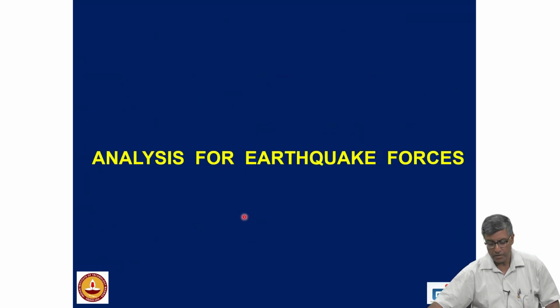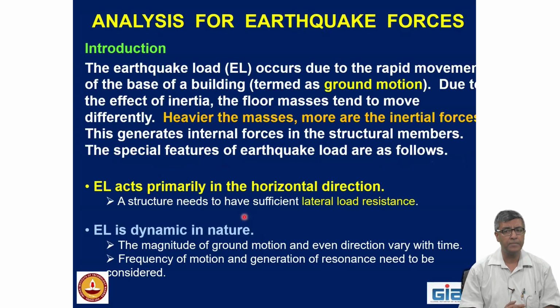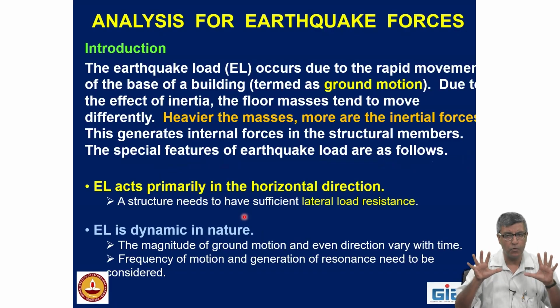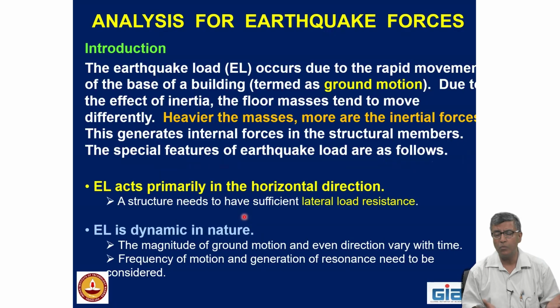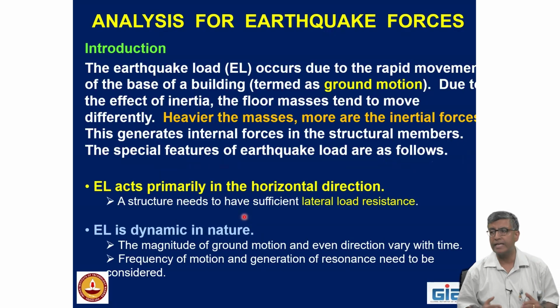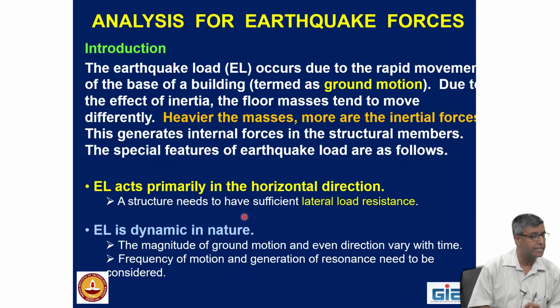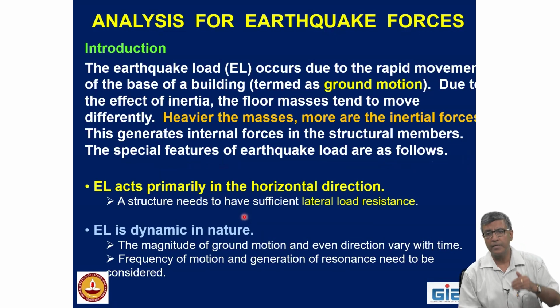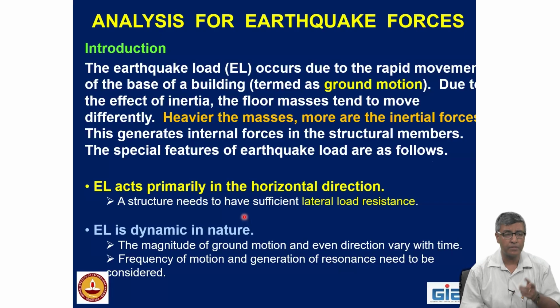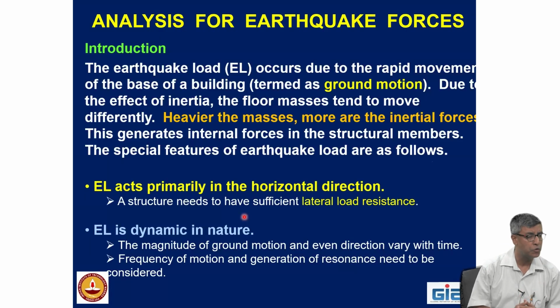Next comes the analysis for earthquake forces. Now, earthquake force is a misnomer. It doesn't apply any force as such. It is a ground motion. And the masses at different levels are not able to keep up with the ground motion because of the inertial effect. Since they move asynchronously with the ground, it generates forces in the supporting members. And those forces, we tend to call earthquake forces. That means it's an inertial effect which generates the forces within the members.